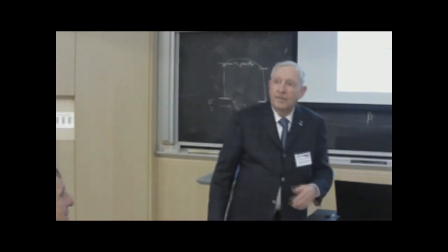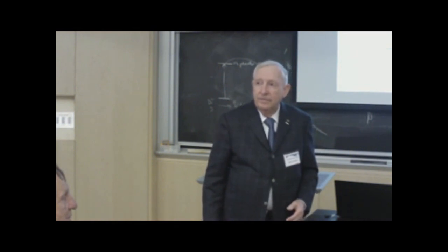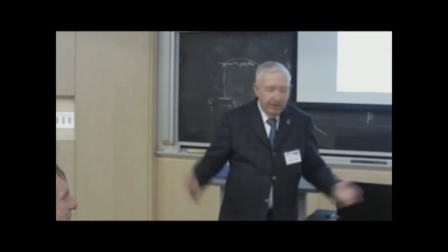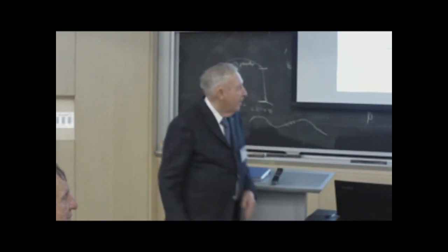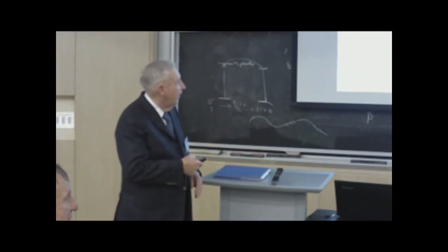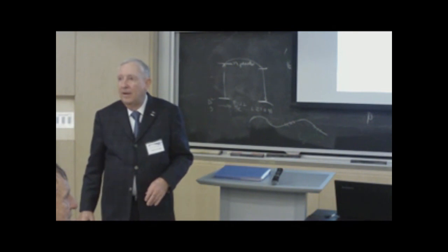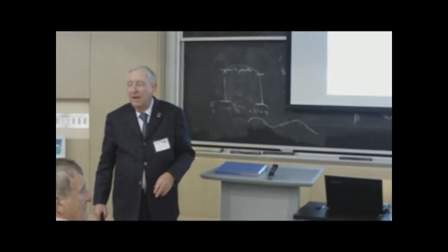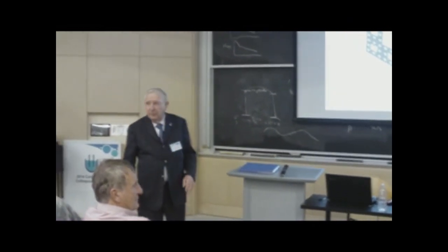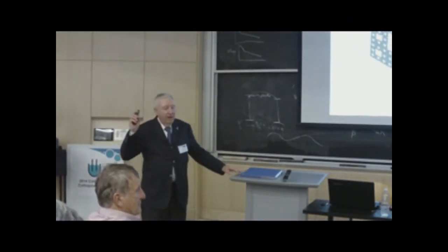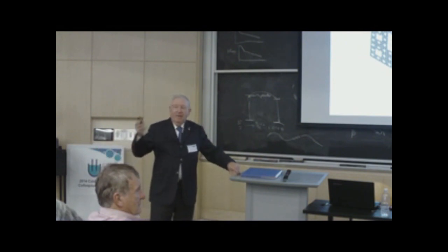Thank you for that answer. What I'm trying to add is that if you do a Menger sponge, you have a variety of different scale sizes. Oh, yeah. Some of those will be resonant structures at infrared. In a Menger sponge, it's possible to get those resonant holes close enough so that you generate a surface wave. So in addition to whatever you're trying to do with your heat pipe, there's going to be another mechanism for heat dissipation, which is effectively a metamaterial surface wave traveling essentially at the speed of light.